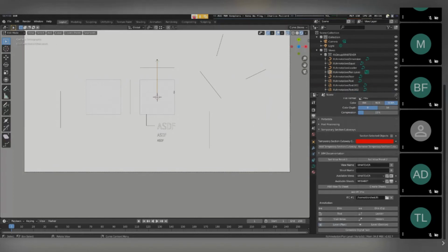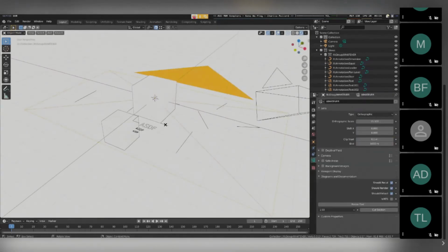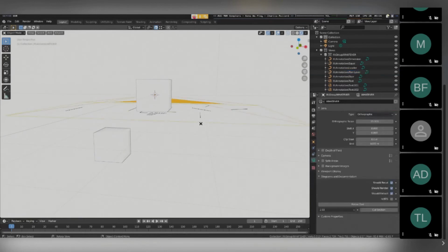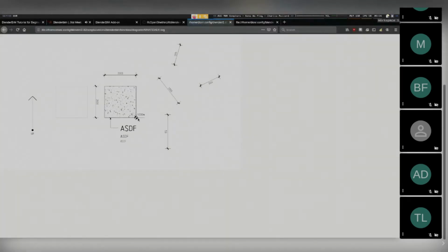A level, we're in a plan view right now. I'll show you both as well. So a level lets you, let's turn on some snapping. Let's say, do that. And what this does is you'll notice it's in 3D. So this is a -1 right now in the Z-axis. And the Z-axis is taken to be the RL. Excuse me.